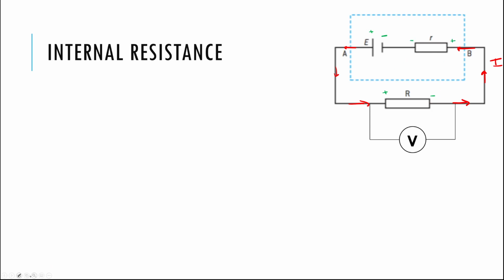And now I can do a loop. I can choose any old loop I want to go through and analyze the circuit. Remember, the loop is not necessarily the same thing as whatever's happening with current. So just to show that idea, I'm going to make my loop start here and go around like this. Why not? So I'll start here and trace my pencil around the loop. And whenever I go through a component, I add or subtract its voltage. And the sum of all of the voltages, no matter which way I trace and whatever loop I pick, should always be equal to 0.